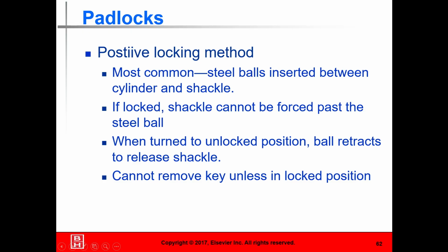The positive locking method, the most common, uses steel balls. If locked, the shackle cannot be forced past the steel balls. When turned to the unlock position, the balls retract, releasing the shackle. You cannot remove the key unless it is in the locked position.